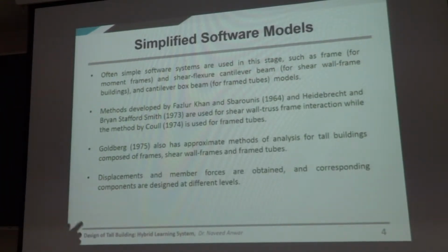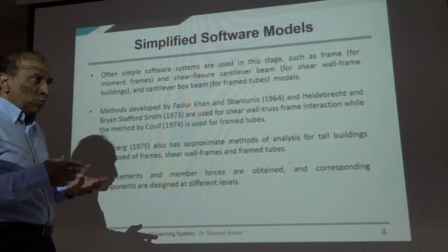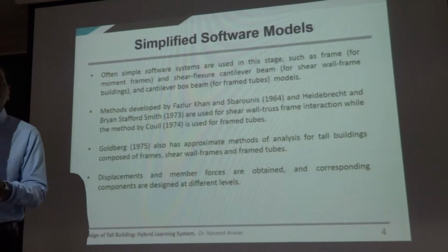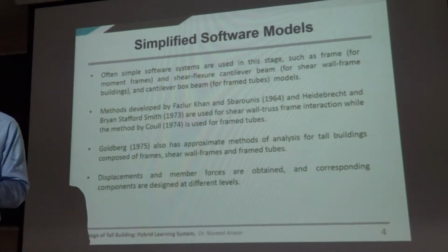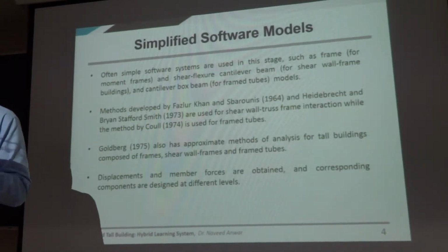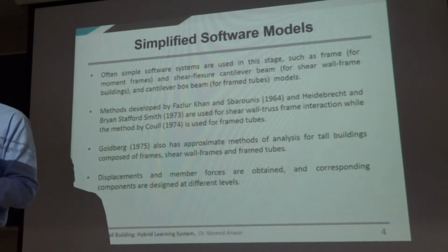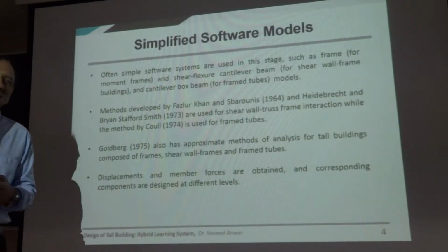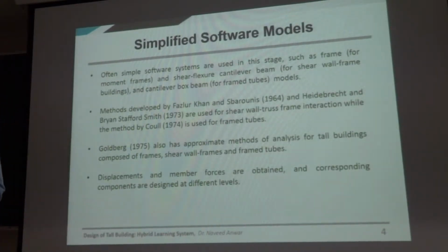But obviously, through experience, we have found that most likely 10 will be suitable for tall buildings. Others may not be suitable for a number of reasons. So out of those 10, you may have to choose 1 or 2 and then compete them to find the right one. But again, narrowing down, experience-based, these days 90% chances are that you will be choosing a post-tension flat slab.